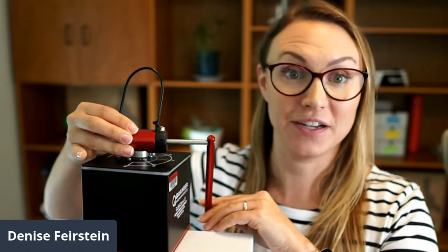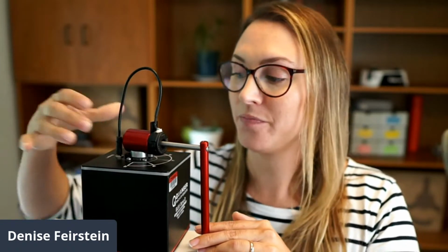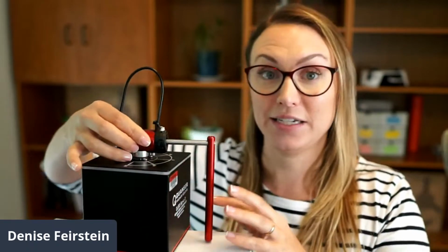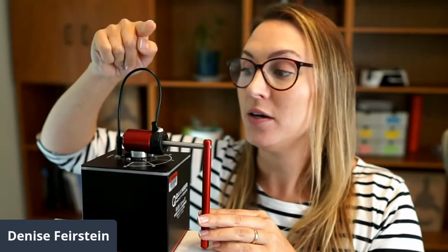We call this alpha, and its velocity, alpha dot. Now, those 4 states can completely describe this system. But let's look even closer at the constraints that we should put on those states and actions. The voltage going in is constrained to plus or minus 3 volts. The motor angle we constrain to plus or minus 90 degrees to avoid interfering with this encoder cable.